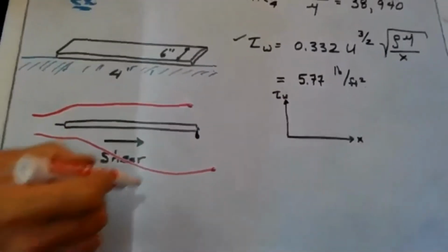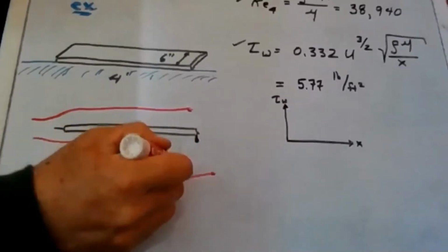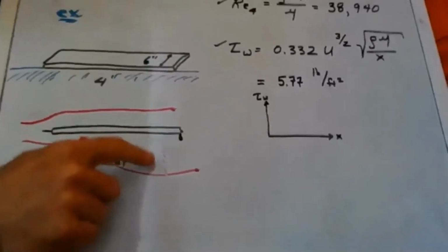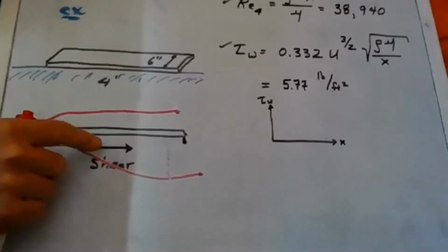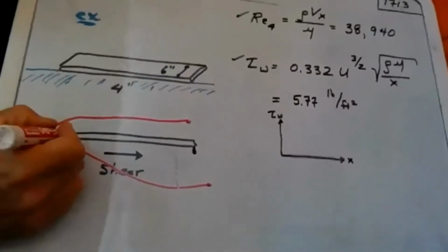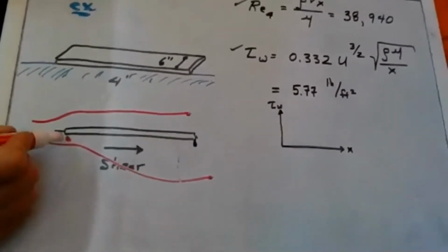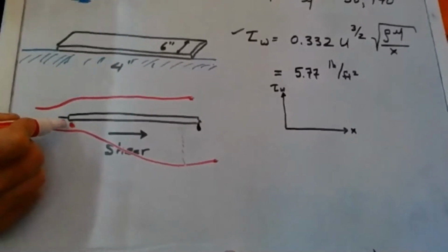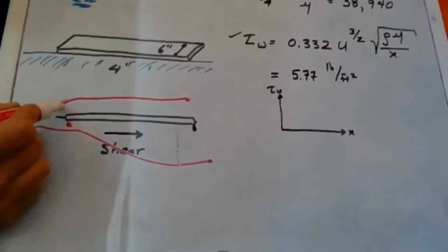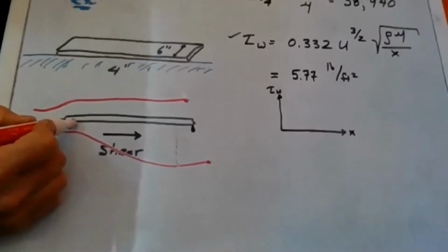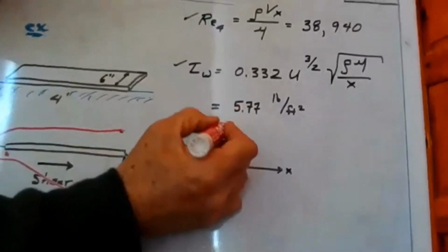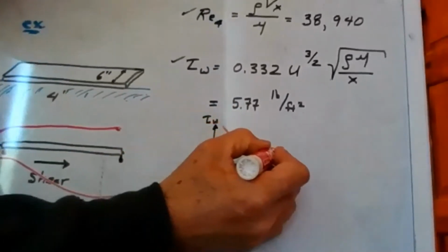Okay. And what we end up getting is an increasing boundary layer thickness, and a decreasing shear the further you go down the plate. And of course, that should make some intuitive sense to you. This first part right here is encountering that engine oil, and we're going to get a tremendous variation in what's going on flow-wise at this point and a lot of shear. Further on, we got less shear going on. And so the classic graph for shear versus x looks like that.